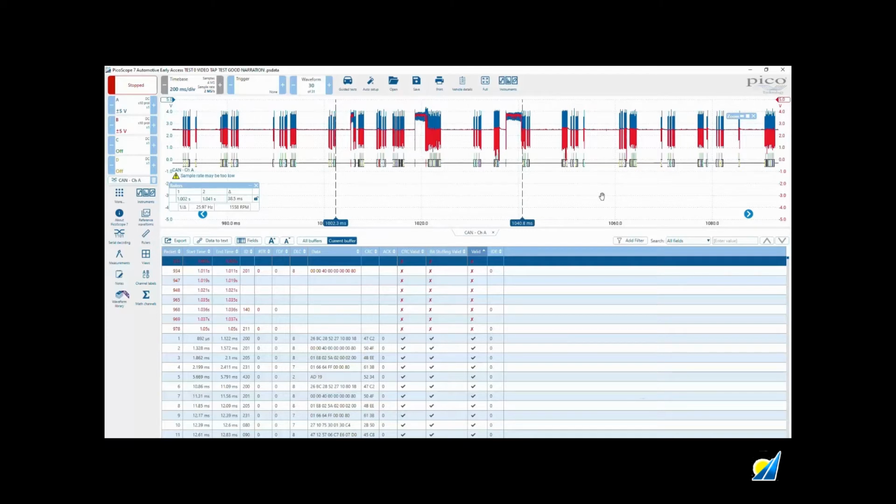That was the instrumentation. Unfortunately, I got both apps paused at that point in time, so I didn't capture the event, but that's when the CAN bus would have been driven high for a long period of time, such that all transmissions would have been halted, and then of course multiple warning lights and multiple errors. So let's now correlate this data here with what we got in Vehicle Spy and see if we can see where the sequence of faults begin and where they end, and what happens in that interval of a fault condition.